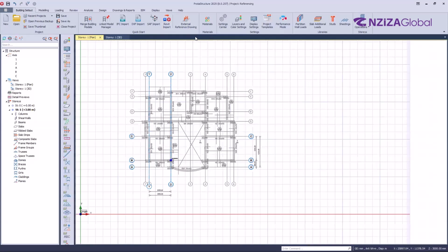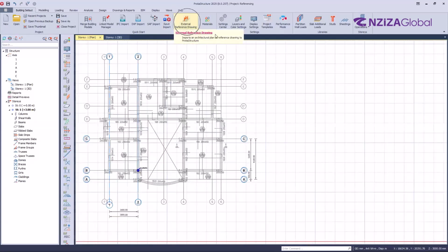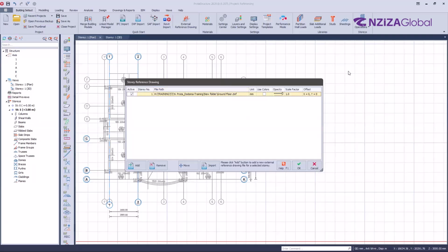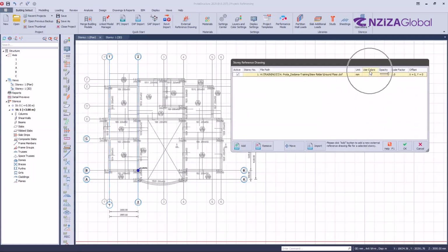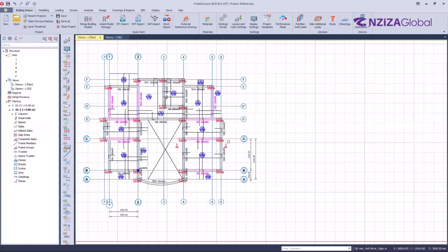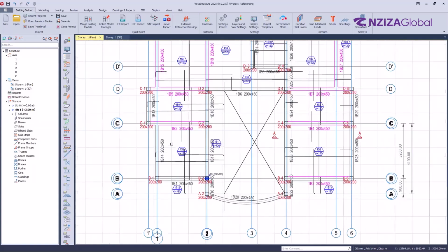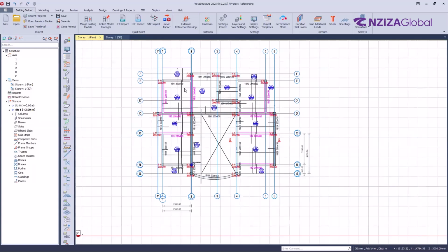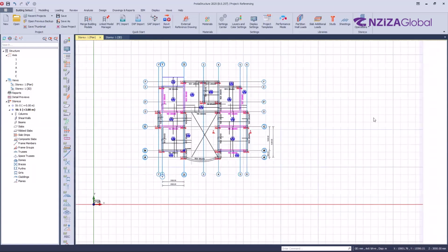So another thing about these settings that we are seeing here, you see we have a use color settings. So if you tick this, now the drawing will no longer be grayed out. It will have colors, the colors that we had from the DXF file. Now we will have colors. Good.